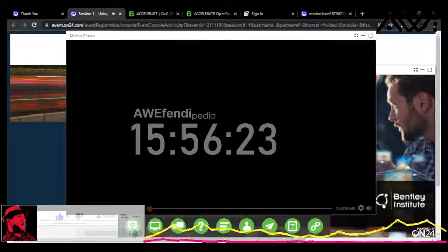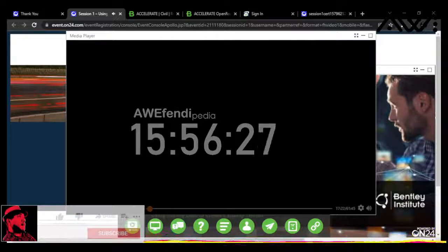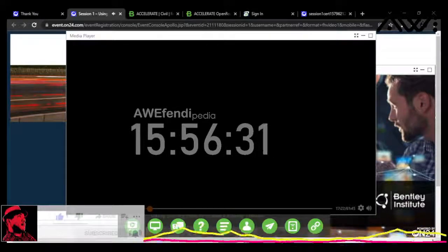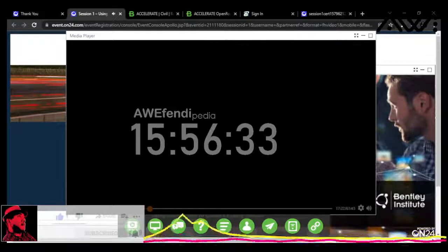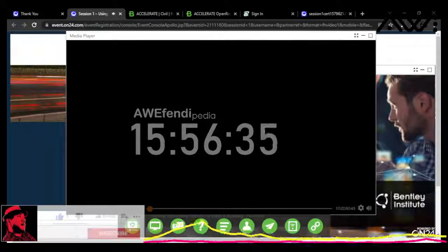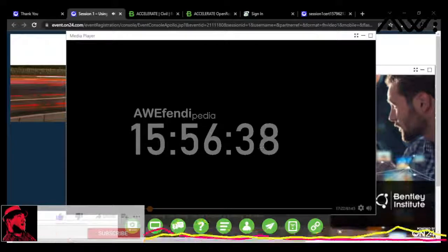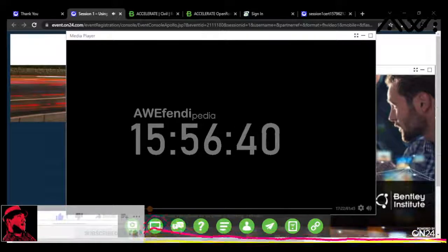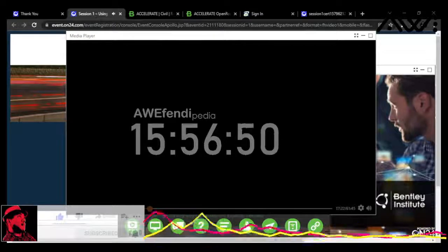And we have our feature definitions. If we expand that, we have our survey feature definitions. So in this DGN lib, we have all of the survey feature definitions ready to go for us to use. And what will happen is when I import my raw data file, it'll look in this DGN lib for the appropriate feature definitions, and then it'll copy it down into the active file, and it'll be using that in the active file.